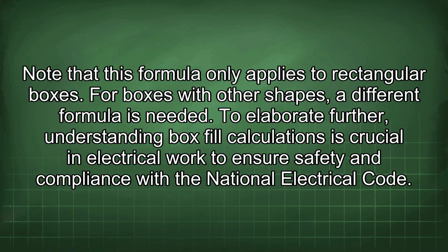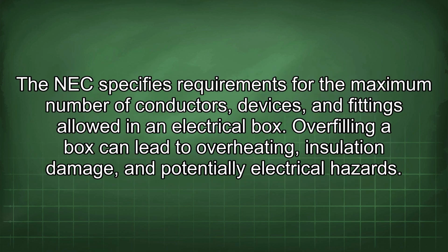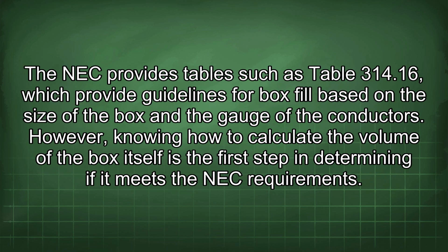To elaborate further, understanding box fill calculations is crucial in electrical work to ensure safety and compliance with the National Electrical Code. The NEC specifies requirements for the maximum number of conductors, devices, and fittings allowed in an electrical box. Overfilling a box can lead to overheating, insulation damage, and potentially electrical hazards. The NEC provides tables such as Table 314.16, which provide guidelines for box fill based on the size of the box and the gauge of the conductors.